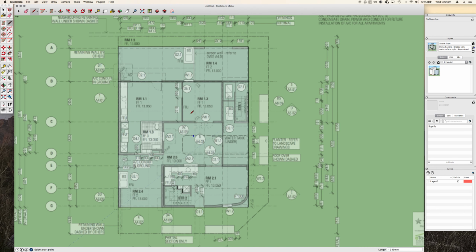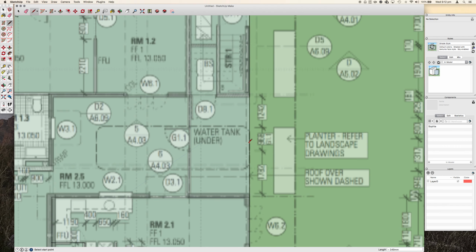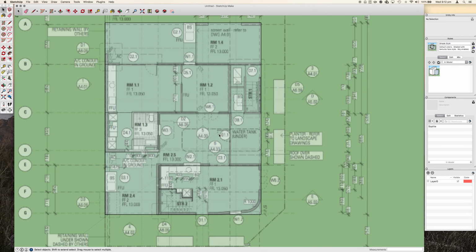Now what I've got is a bunch of floor measurements, as well as area measurements, as well as linear meter measurements. And this is a residential design, pretty small project. Obviously the budget's going to be pretty low for this type of work. So I'm not going to get too accurate on this one in terms of my horizontal plane measurements. So I'm going to have to make some kind of guess about window heights and door openings and things to subtract from the wall areas.